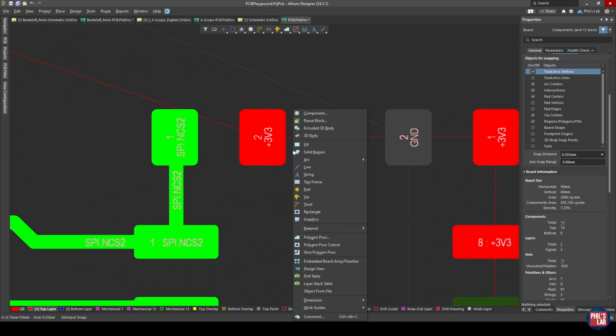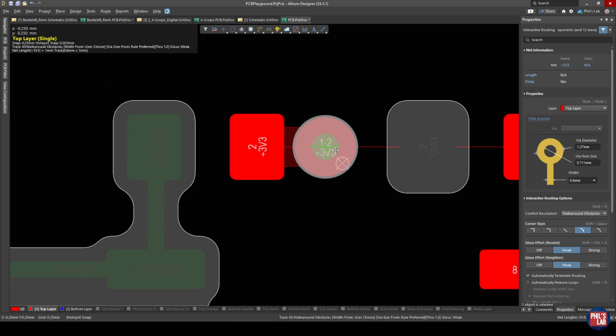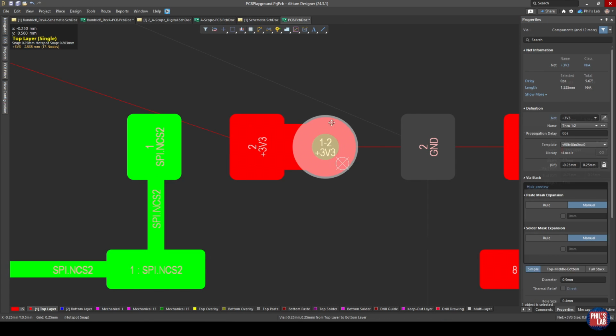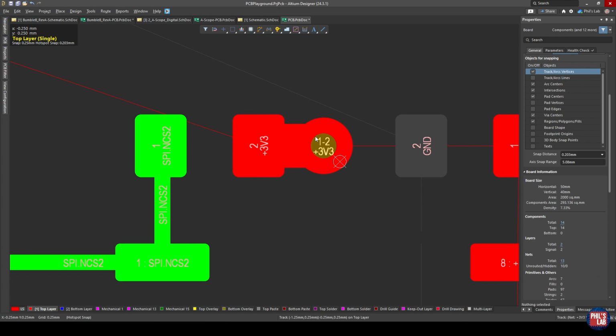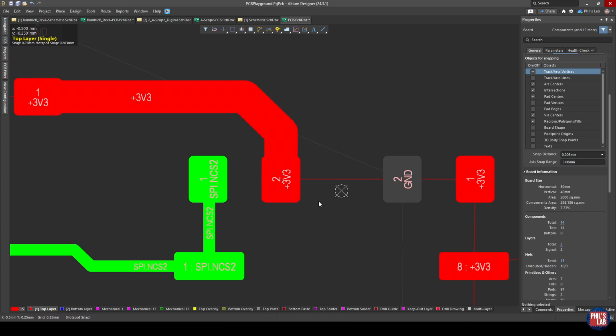On the other side of the pull-up resistor, if I have an internal power plane, I'll place a via very close, but not too close to the pad, and a short wide trace from the pull-up side of the pad, short wide trace into the power plane via. Or if I'm doing routed power, I would simply have a wide trace coming from my other power traces.